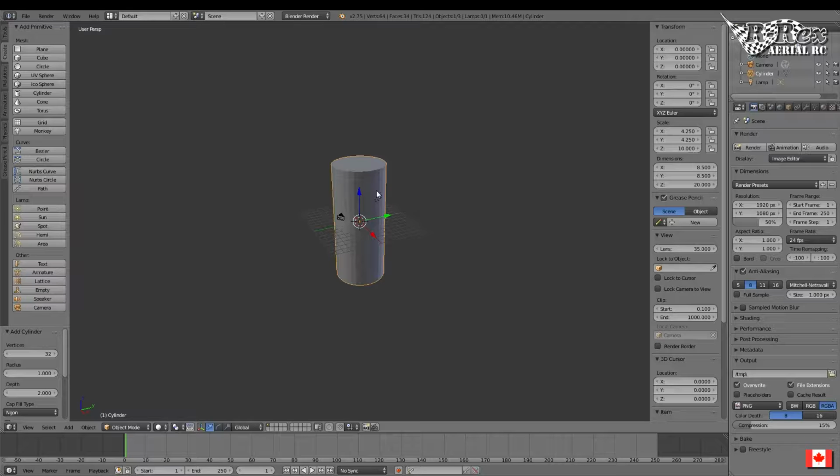Now, you're going to have to remember, though, 3D printers aren't exact. There's going to be overlap all the way around. So when it tries to print a cylinder, it'll actually print slightly smaller than a cylinder as it extrudes more into that cavity. So I want to add a little bit of clearance. What I'm actually going to do is set this to 8.7 by 8.7. It's not much, it's 1/10 of a millimeter, but it'll make it easier for the motor to fit inside of the frame when we're done.